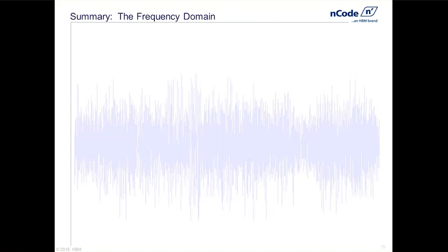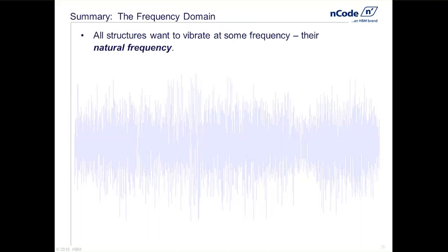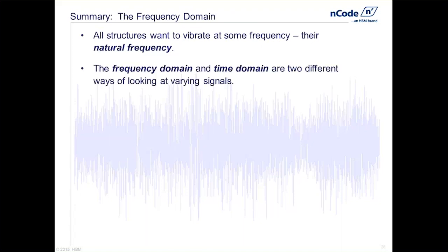And now I'd just like to wrap a couple things up in a summary slide on the frequency domain, just to state that all structures are flexible structures, and they will want to vibrate, and because of their mass and their stiffness and the way in which they may be constrained, they will have certain frequencies they'll want to vibrate at more. These would be natural frequencies.